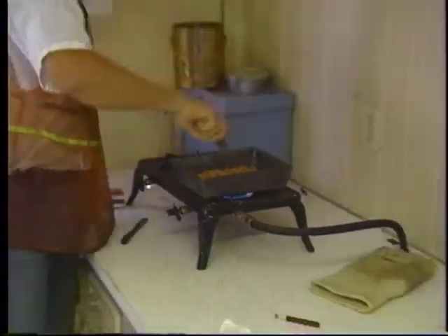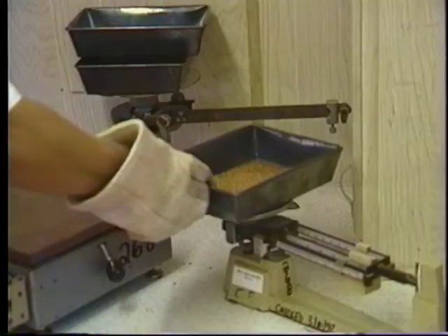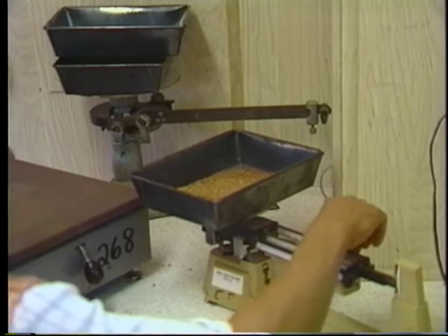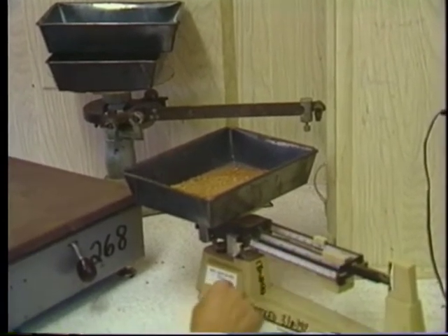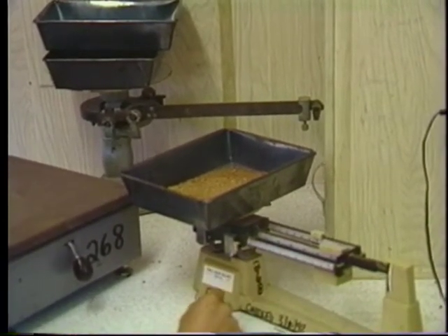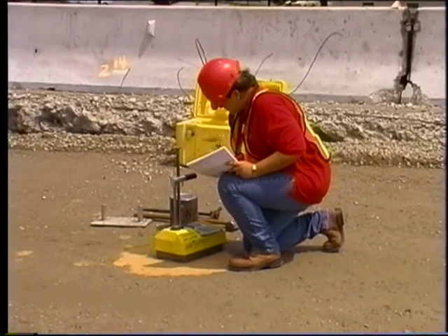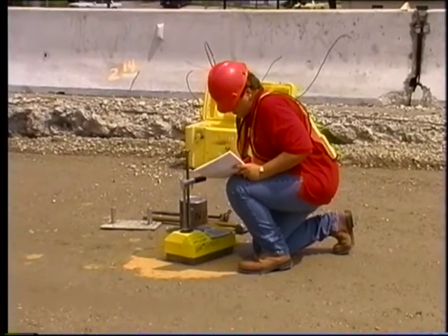Use the moisture from the stove or oven drying methods. If the moisture from the nuclear device is within plus or minus 0.5% of the stove or oven drying moisture, you can use it to calculate dry density and percent density. Record retest results on additional forms.